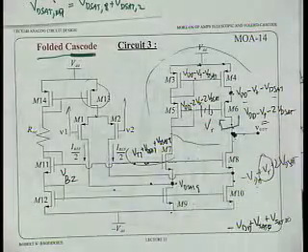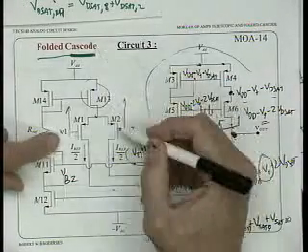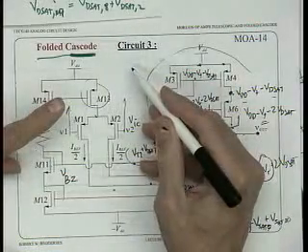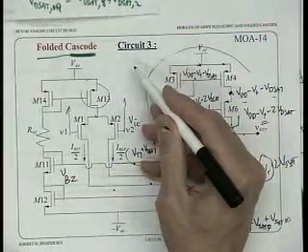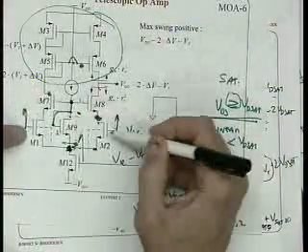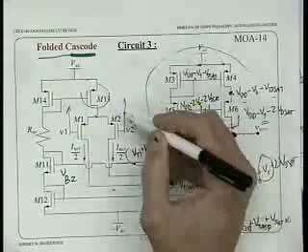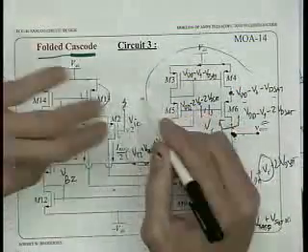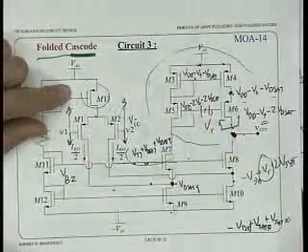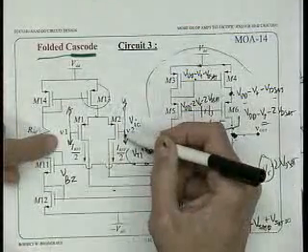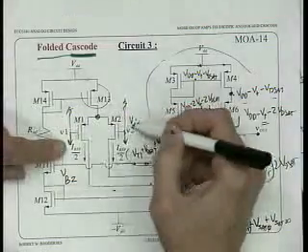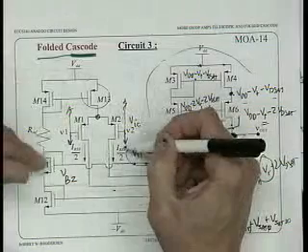Okay, so you're worried about, let's take a common mode voltage. Which way should I go with this common mode voltage? Up or down? Up? Here our problem was when we took the common mode voltage up on M1 and M2. So let's worry about the case when the common mode voltage goes down. This is flipped over, right? It's kind of the same issue. So this voltage right here will track and start following this input common mode voltage going down.